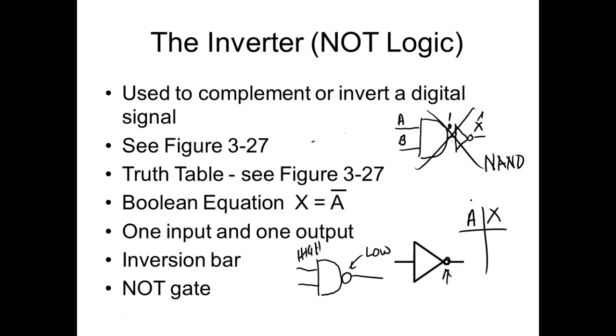They're going to respond to a certain logic. So an inverter, if the input is low, the output's going to be high. If the input is high, the output is low. So this is telling us what's going on between the input and the output. We do have another one, which is not a logic gate, called a buffer. That guy does no logic, so it's not considered to be one of the 5 basic gates.